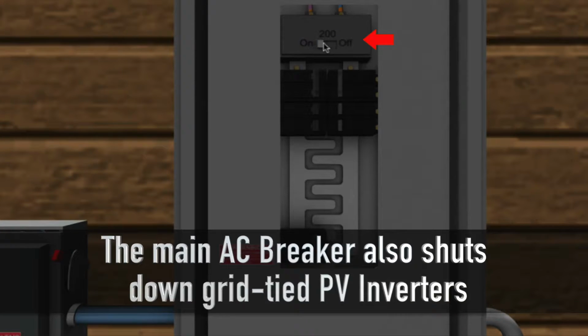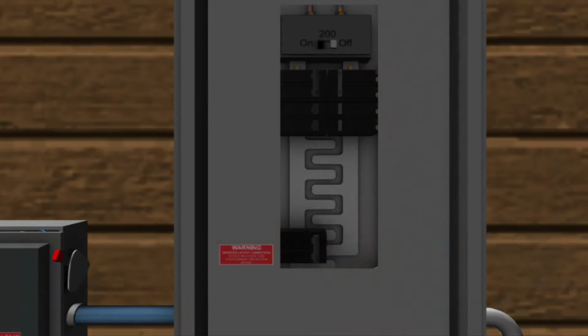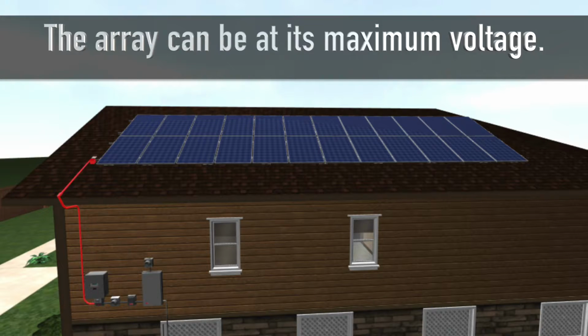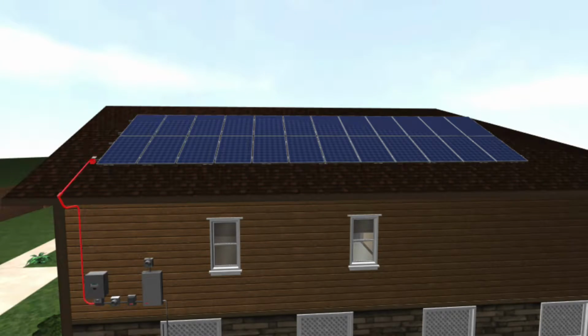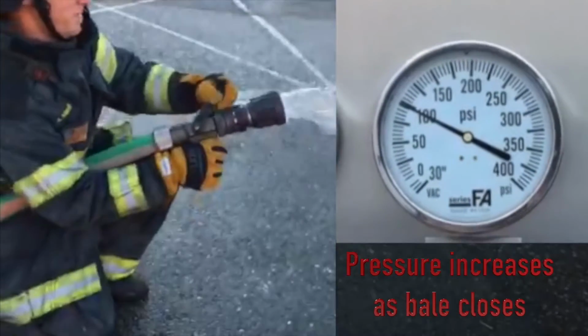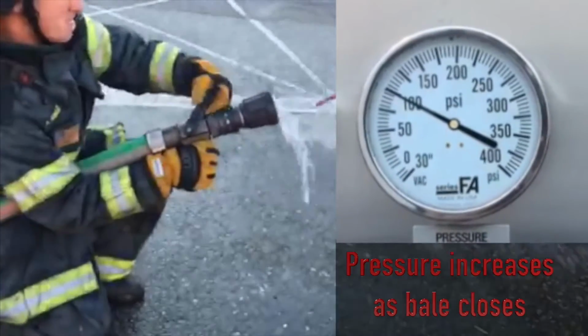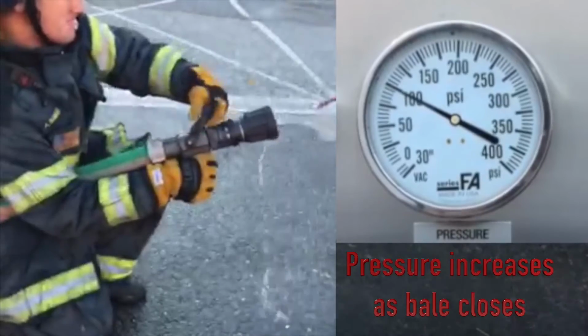It's important to know that when the inverter is off, the strings up on the roof and the wires coming off may be at their maximum voltage when light's exposed. This is similar to closing the bail on a hose line. The pressure will go up a little bit, but there's no water or current, in our example, flowing. The pressure, or voltage again, is still there though.